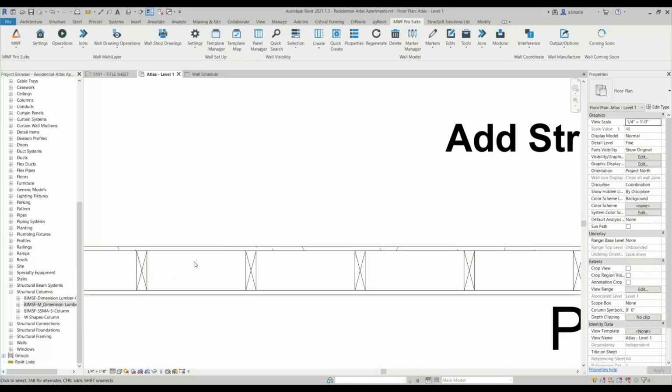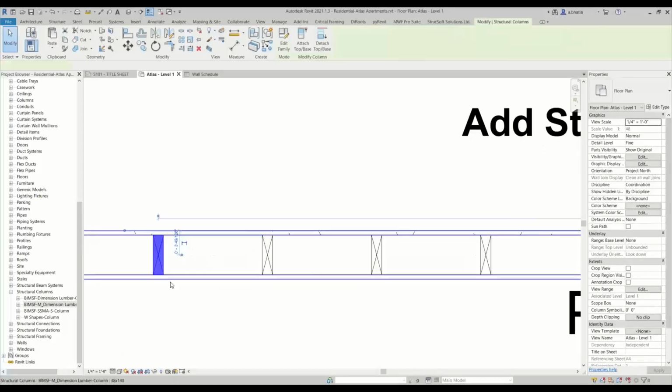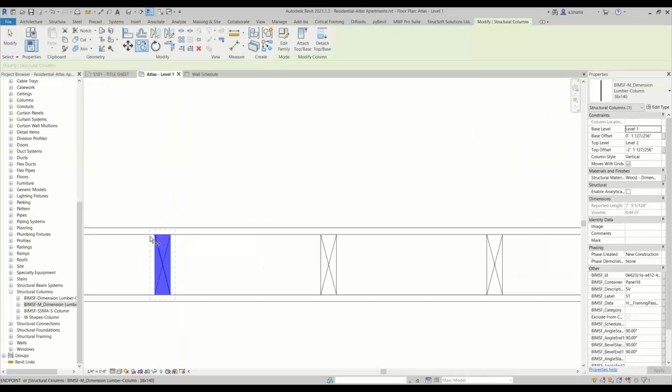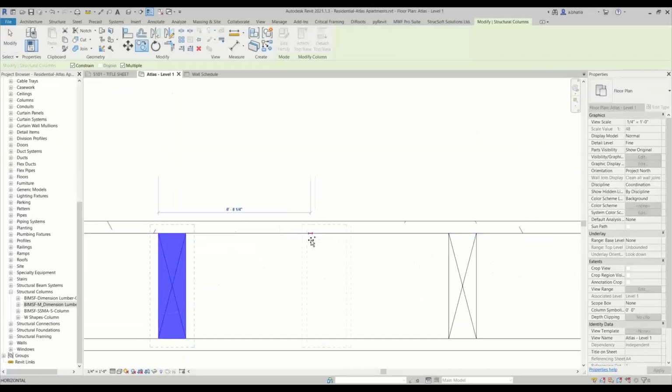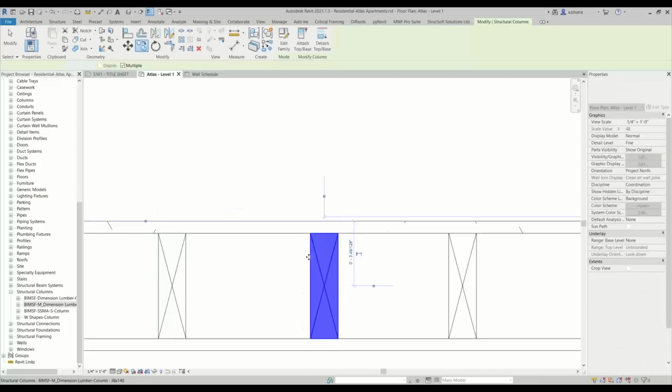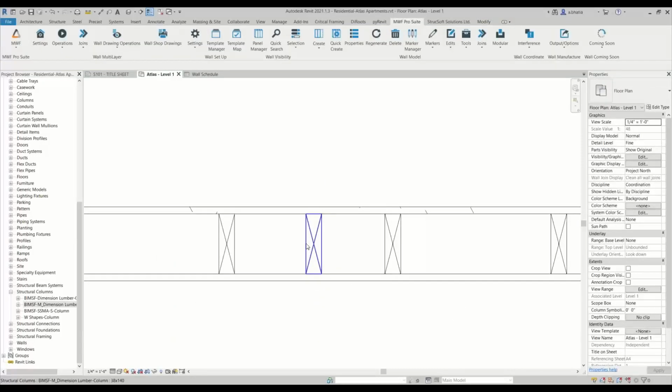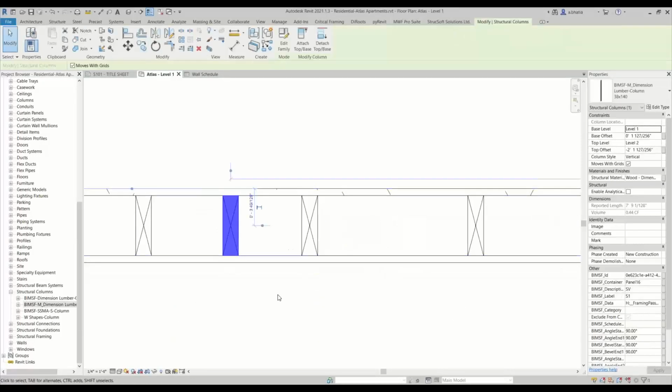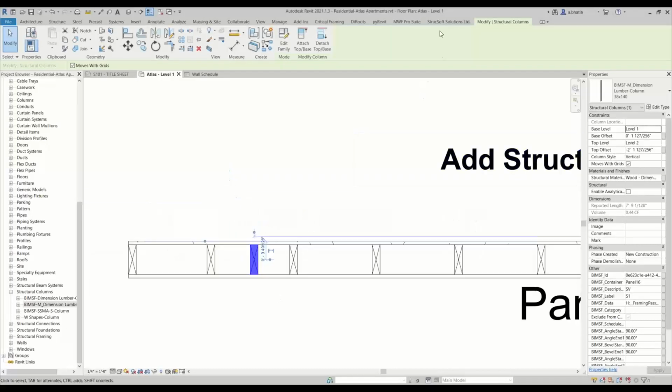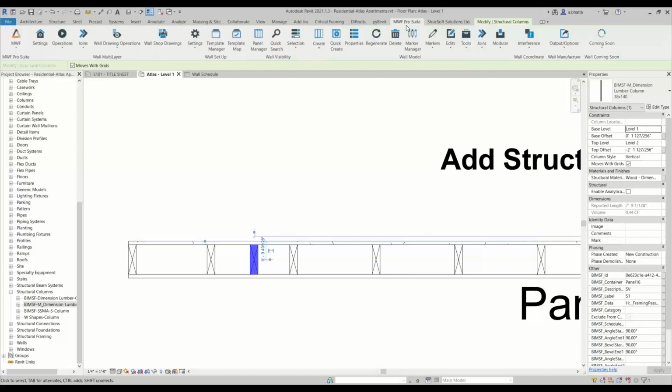So you don't want to mess with the spacing, but you just want some support over here. You could copy the existing stud that we have here, just using Revit copy, and place the stud there. And then you could click on the stud, and now we can try to add it to the panel, right?